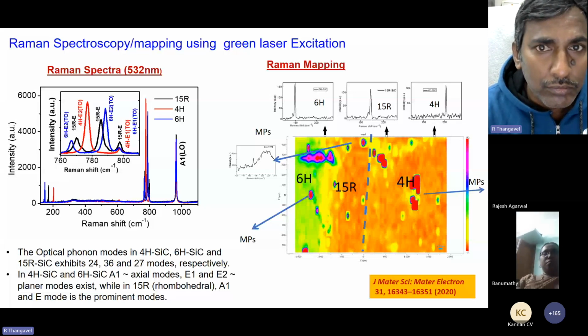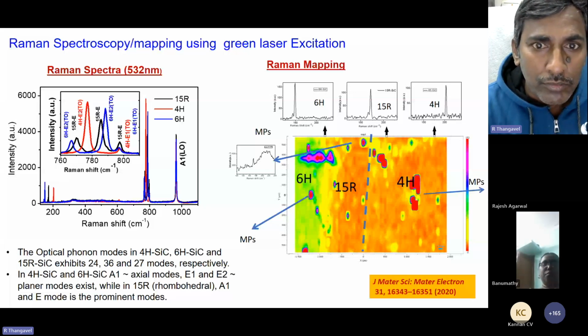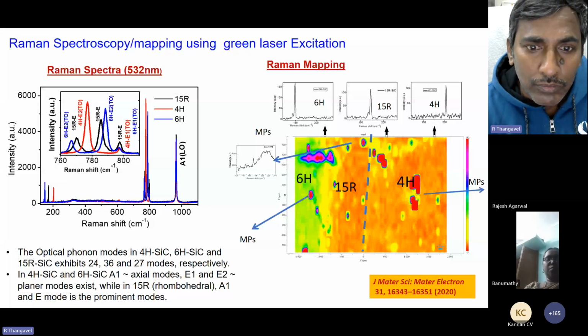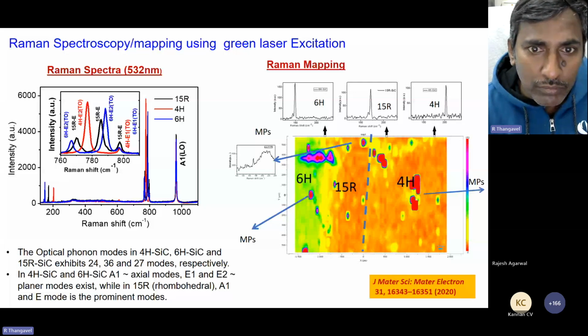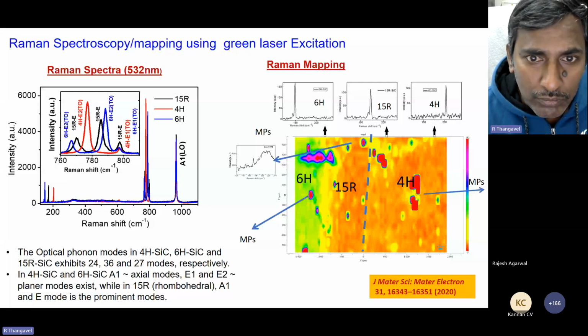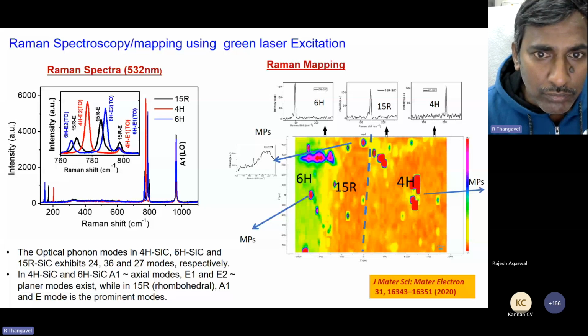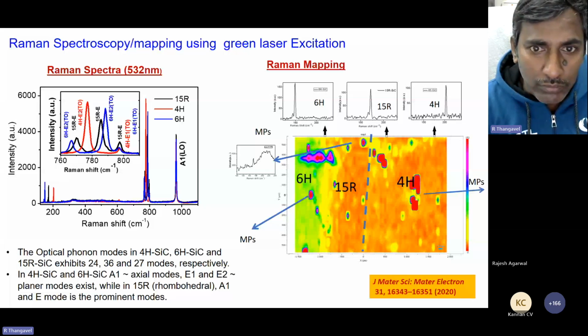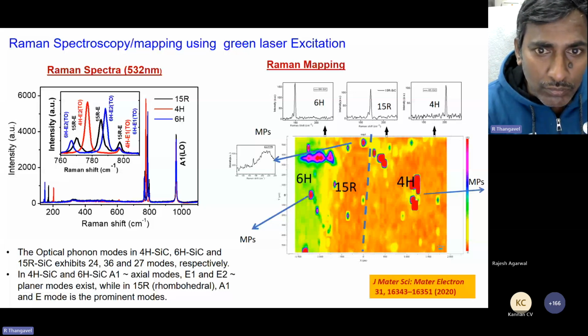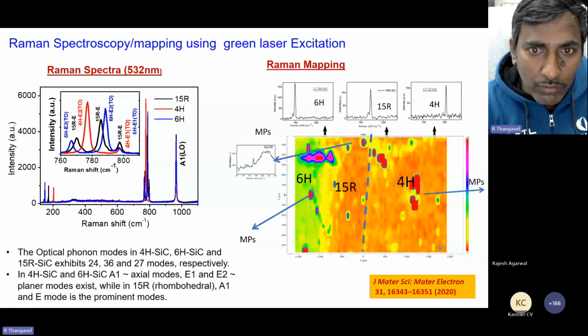Now, in the semiconductor device fabrication process, these are the steps which have to be used for the final device up to test and assembly. First, the device has to be designed properly. Then, after designing, the wafer preparation. Wafer preparation means whatever wafer we have, it has to finally become a proper epi-ready wafer. After the epi-ready wafer, the front end process can be done. In the front end process: photolithography, etching, cleaning, thin film, dielectric and metal deposition, ion implantation.